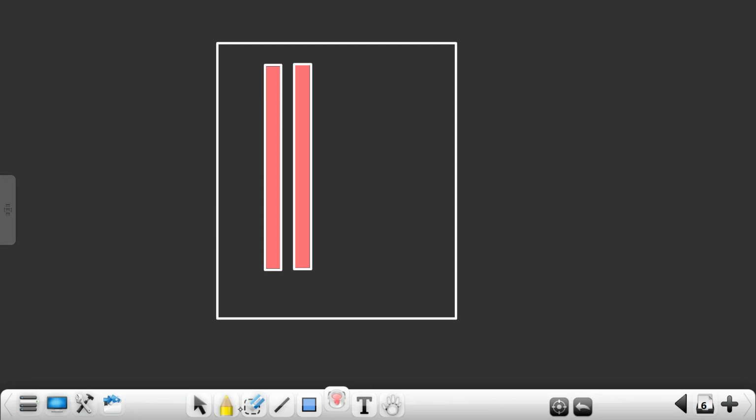How to remove? Treat this metal with some highly concentrated acid. This metal layer will get eroded, it gets melted and that will be removed. But this region gets unaffected because it is already covered through the oxide layer. So only in this region I have a metal layer. Creating a metal layer at this location is not like a grinding process, it's a chemical process.